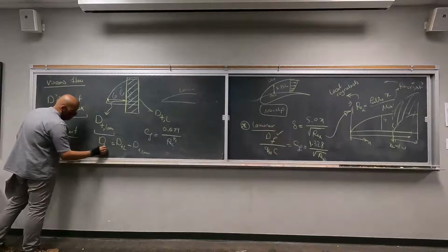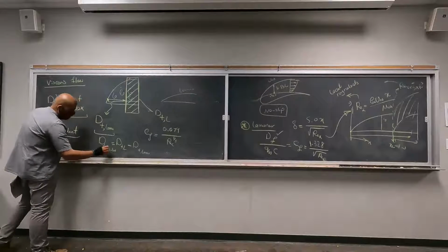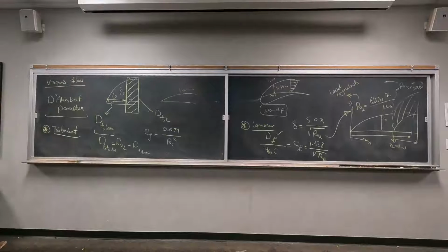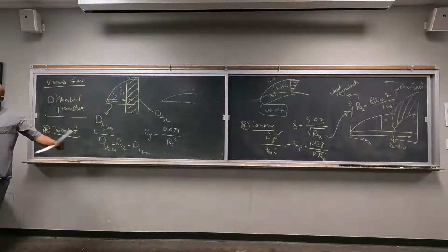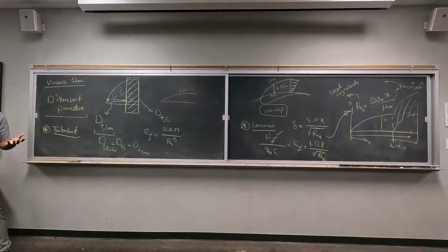The turbulent drag, let's call it. Does this make sense at all? So essentially, you assume that all of the plate is turbulent, do the calculation, then you remove the part in which the flow is really laminar, right?